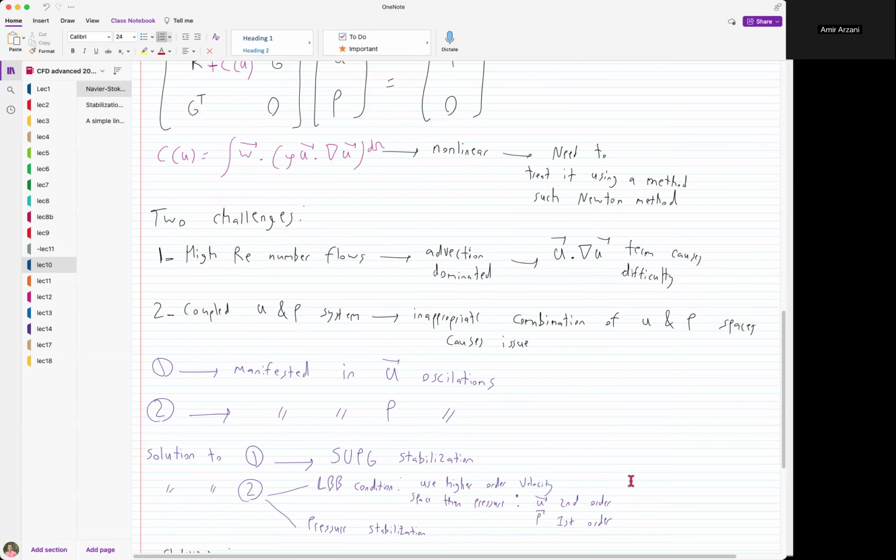But in FEniCS, this is pretty easy. You just select 2 for the order of your shape functions. If you cannot use a higher order velocity space, either because of implementation issues within your code or because of the high computational cost, second order velocity in a 3D mesh typically means about 8 times more degrees of freedom.